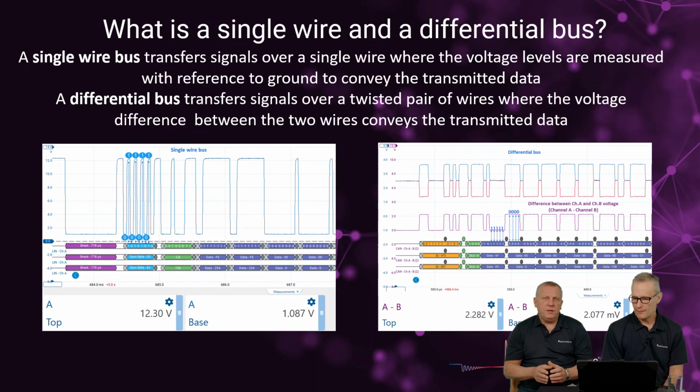So in non-safety critical systems, you can get away with using a single wire, because if that function fails, for most things on a single wire network, there'll be some form of redundancy. It could be manual redundancy. So if you think about automatic lights, the driver can still have the option to turn the lights on themselves. So it's not safety critical, and that's a feature where you'll see a single wire network.